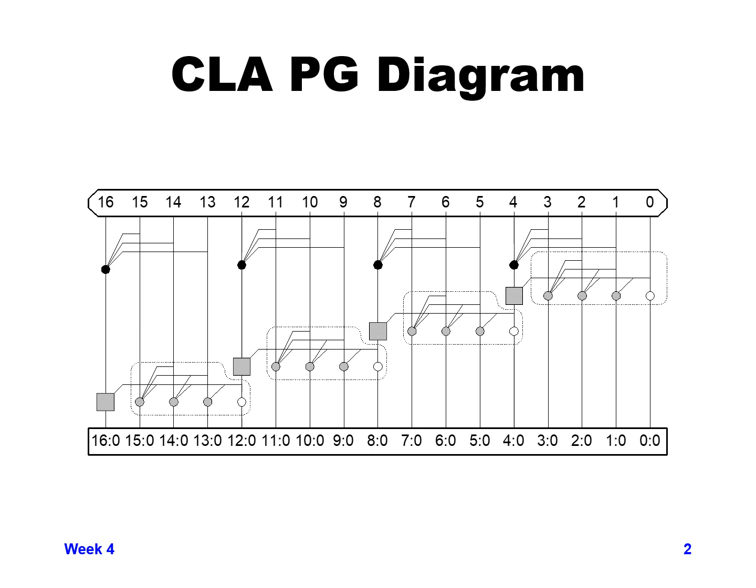Then we go through that carry skip at bit 4, skip to the left to bit 8, and do a normal carry skip again at bit 8, skip to the left to bit 12. So we've gone through 3 of these normal carry skips.